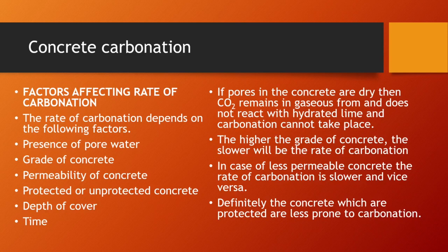And then the formwork is built around that tightly up to these blocks. In other words, there will be 50 mil of pure concrete between the outside and the steel reinforcement bar when it's all cured and when it's all one big concrete block. And that's what they mean by depth of cover.